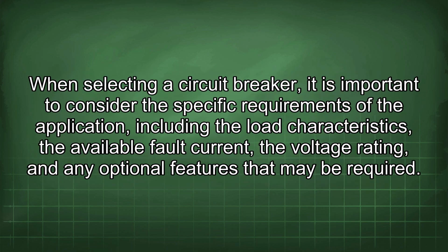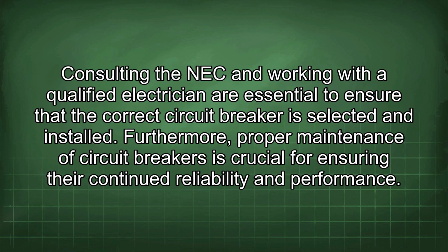When selecting a circuit breaker, it is important to consider the specific requirements of the application, including the load characteristics, the available fault current, the voltage rating, and any optional features that may be required. Consulting the NEC and working with a qualified electrician are essential to ensure that the correct circuit breaker is selected and installed. Furthermore, proper maintenance of circuit breakers is crucial for ensuring their continued reliability and performance.